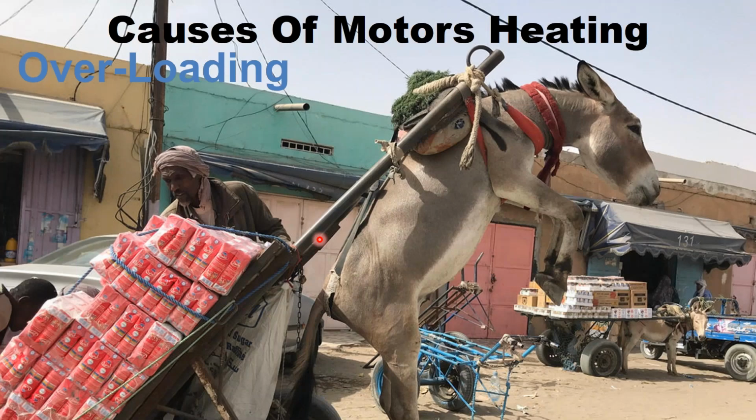Overloading. Here we have our donkey who's overloaded. He can't move anywhere. He's basically stuck. But in the case of an overloaded motor, individual motor components, including the bearings and windings, may be working fine, but the motor is going to continue to run hot. The primary symptoms to look for here would be excessive current draw, insufficient torque, and even overheating itself.